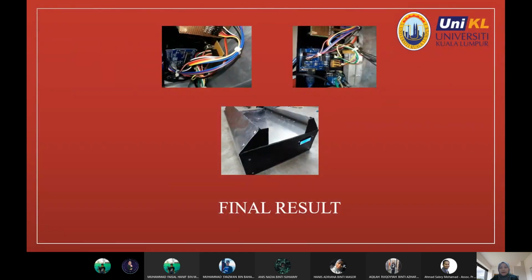So this is my final result. Actually, at the top of the prototype, a thick rack will be placed and act like a mattress, and the heat generated from the heater and fan will spread all over the surface. A thermistor will be placed on the back of the patient body to detect body temperature, while the humidity and air temperature sensor will be placed on the front of the project to more easily monitor the humidity and air temperature. I put the heater and fan in the PVC pipe to ensure the hot air reaches the entire surface. That is how my prototype works.